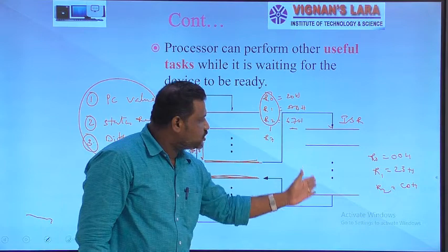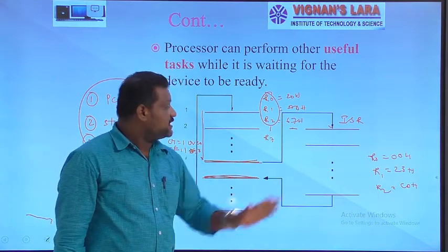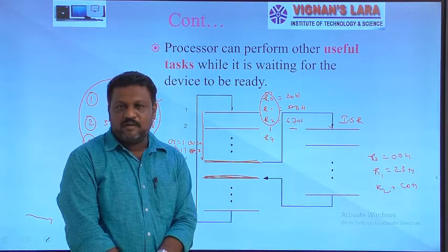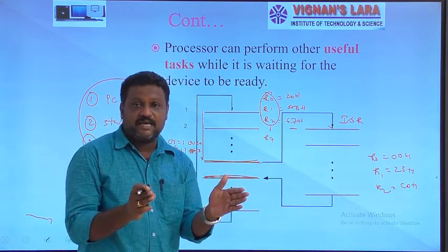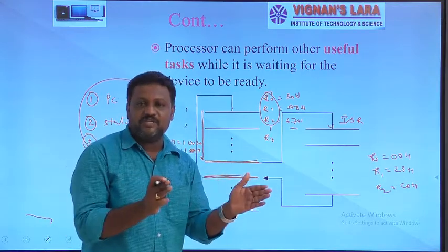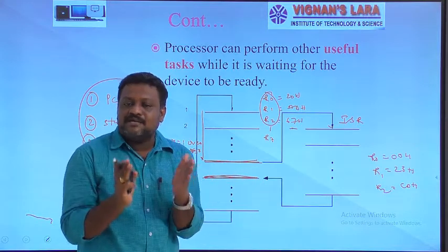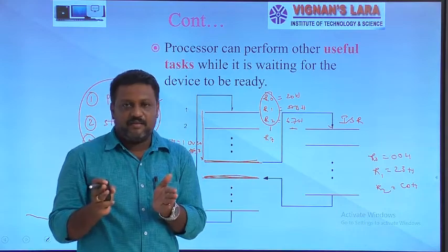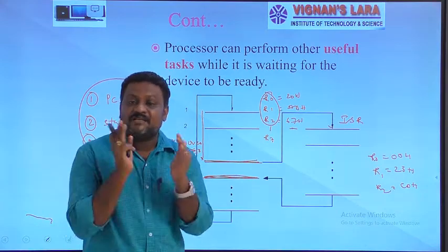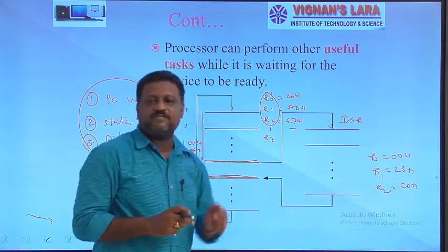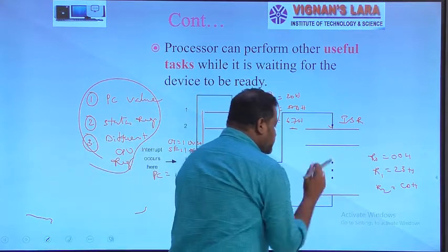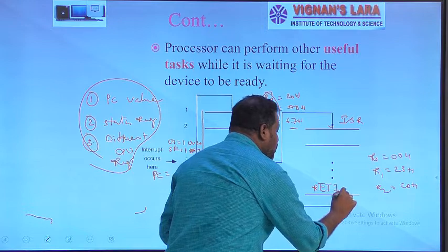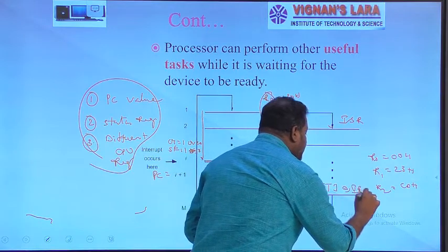Then we start the execution of the service routine. We successfully execute all the instructions present in this service routine. I clearly told you in the last class, guys, when I was talking about the branching instructions, one of the unconditional branching instructions, IRET or RETI, we use as a terminating instruction for the interrupt service routine. It means here the last instruction may be RETI or IRET.